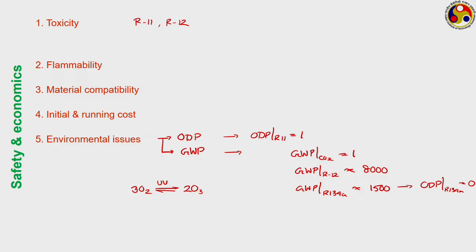So, the kind of refrigerants which have chlorine in their molecular structure, when those refrigerants get released in the surrounding, and when they are able to reach higher atmosphere, then they generally decompose, leaving free chlorine into the surrounding, and that free chlorine can react with the ozone to get it converted back to oxygen, thereby causing a depletion in the ozone concentration in the upper atmosphere. That is what we refer by this ozone depletion potential.